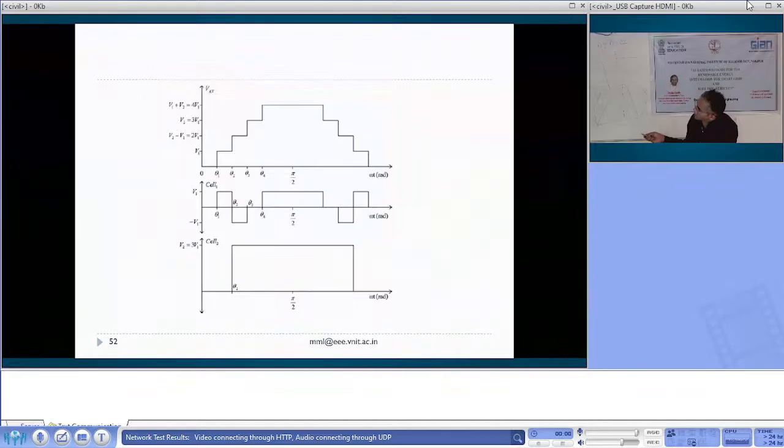So this is the waveform obtained as a combination of two H-bridges. The bridge which is of low voltage has more switching, and the bridge which has a high voltage has less switching, and we get the combined waveform like this. It is more close to sinusoidal, so you produce less harmonics also.